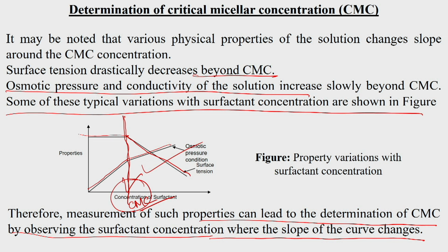And if we want to use this concept to separate the solute particles from the bulk with the help of a membrane, then our surfactant concentration should be well above the CMC, so that the monomers form globules, and the globules attract the solutes. Then with the help of membranes with bigger pore diameter, we can trap the small diameter solutes, and that is the beauty of the micellar-enhanced ultrafiltration process.